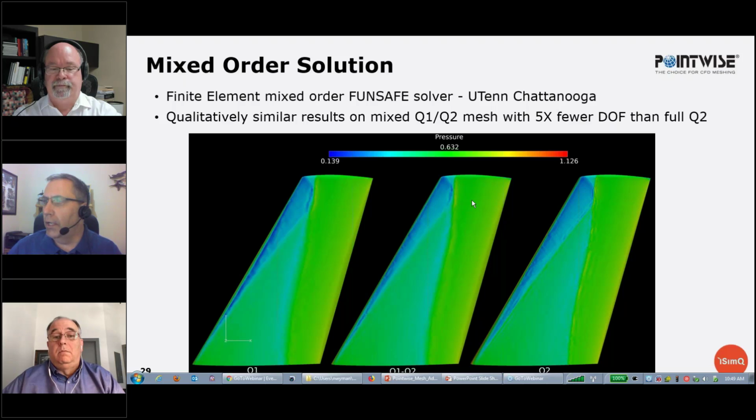Good point. I have a couple of questions which are a little bit related. One is, how do you account for mesh sensitivity in adaptive meshing? I think what was meant by that is, if you have a coarse mesh and you adapt to features on the coarse mesh which may be poorly resolved, how do you know that you're not driving the solution in a direction which is not what you might have gotten with a fine mesh in the beginning? And related to that is transient or unsteady simulations, where you have flow features which are migrating around. What would be done there?